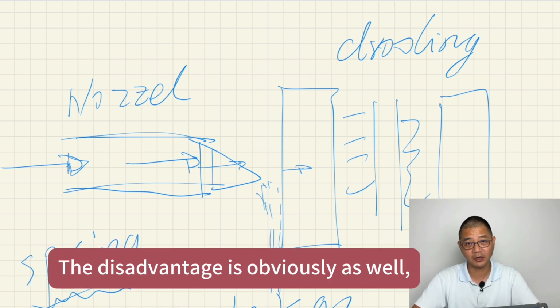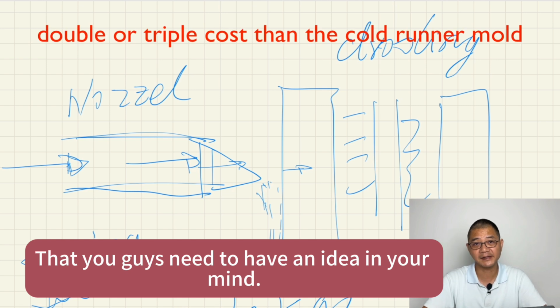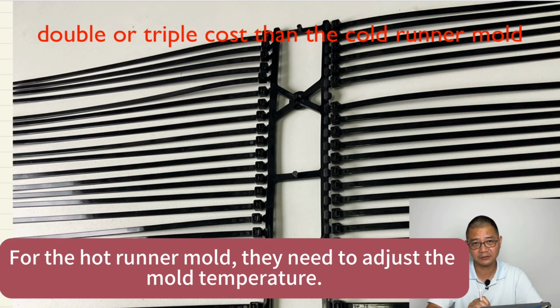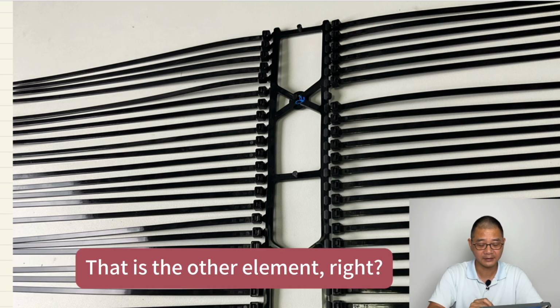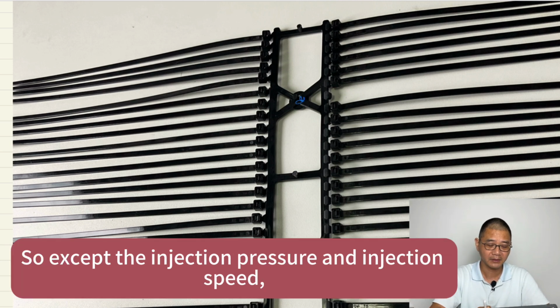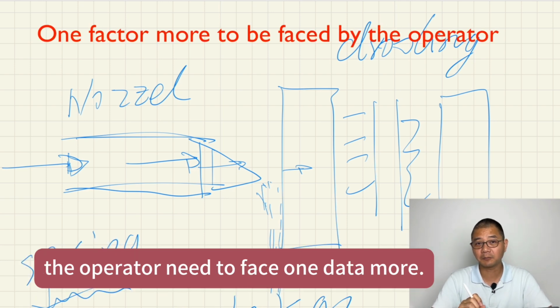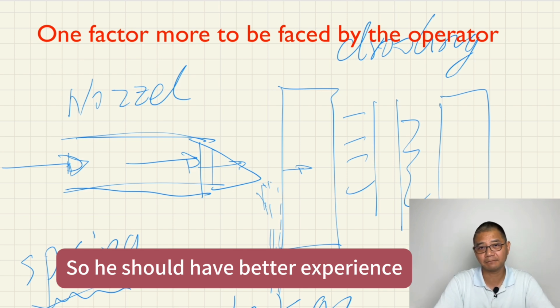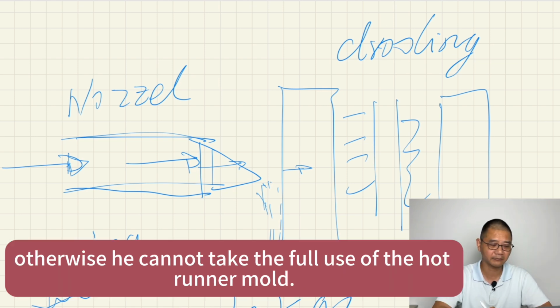The disadvantage is obviously cost, double or triple the cost of the cold runner. Then you guys need to keep in mind that for the hot runner mold, you need to adjust the mold temperature. I mean adjust the melting point temperature. That is another element, right? So besides the injection pressure and injection speed, the operator needs to face one more parameter. So he should have better experience, or he should be more skillful, right? Otherwise he cannot make full use of the hot runner mold.